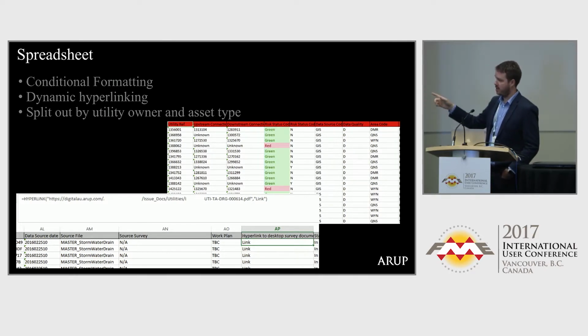But if you ever want to output a formula to Excel, just do the attribute name and then .formula at the end, and just type the formula as you would in Excel, which is really quite useful. At first I was a bit skeptical, but it was useful to output the links for the guys.